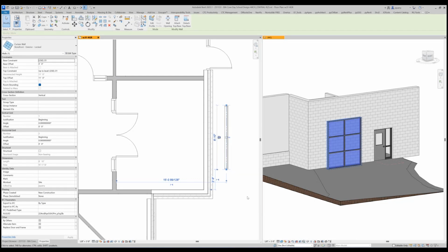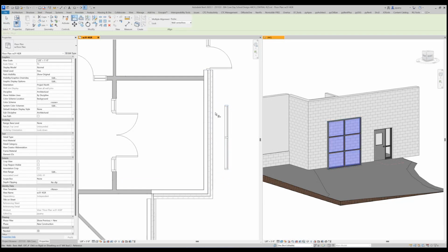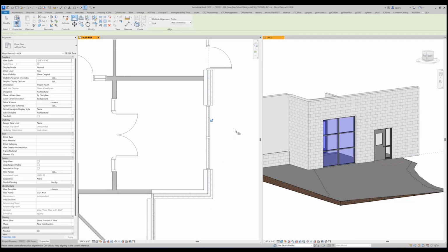So it works. It's got autonomy. It's like a ceiling grid being connected or something. Yep, that's exactly what it does. It auto joins to something that's next to it. And if you don't disallow join, then if your groups are different, you get the warning that says all groups are not the same. What do you want to do? Do you want to ungroup them all, or do you want to create a new type? Well, you don't want to do any of that. So you'd be better off just to cancel that, come in and disallow the joins, then proceed with moving it into place. So let's go ahead and put this back. That's a big tip, because that has annoyed me in my life more than you can know.